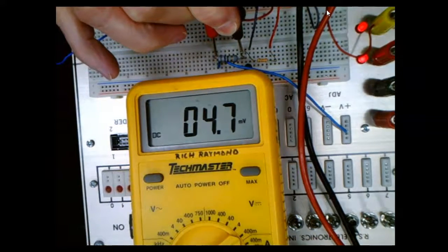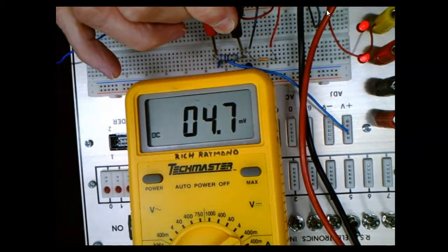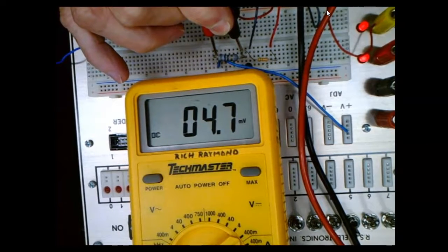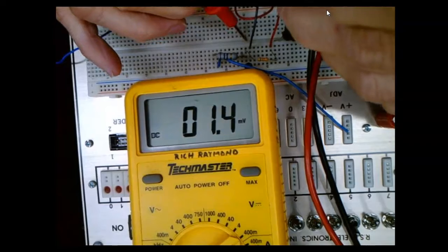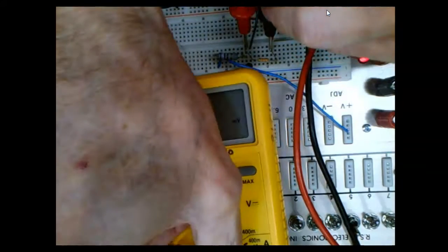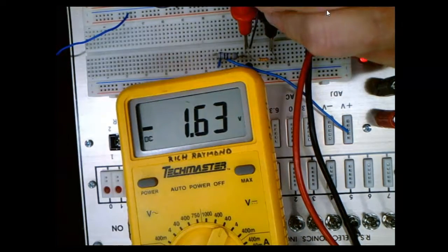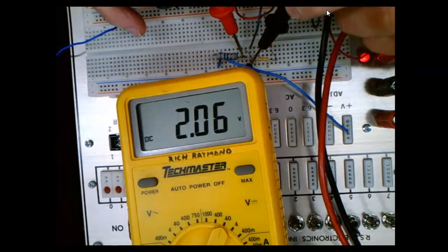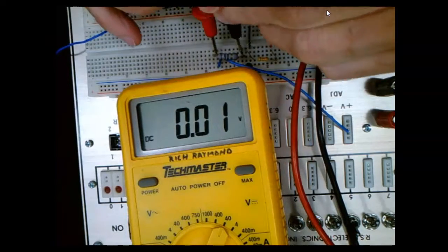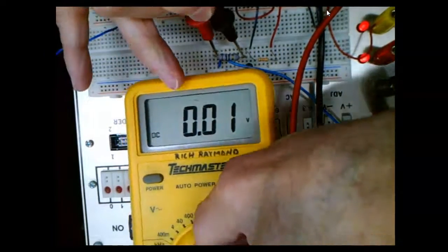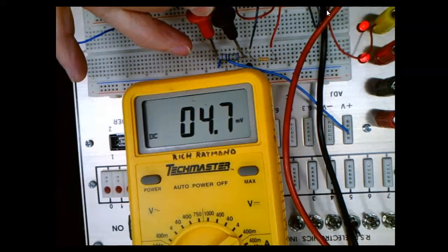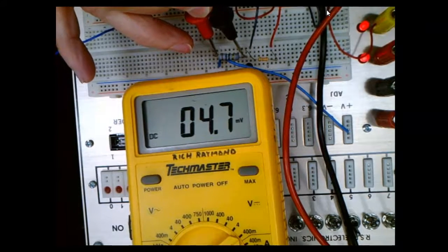So we have 4.7 or 5 millivolts across my collector resistor. So what would be my current? Yeah, 5 millivolts, 4.7, 5 millivolts. I thought I did too, but here's across my base resistor. We have 0.63 volts. Here's my emitter to collector voltage. We're supposed to have 2 volts. Okay. And this is across the 100 ohm right here. So that's 5 millivolts. So what would I see there? Oh, 50 microamps. Yeah.